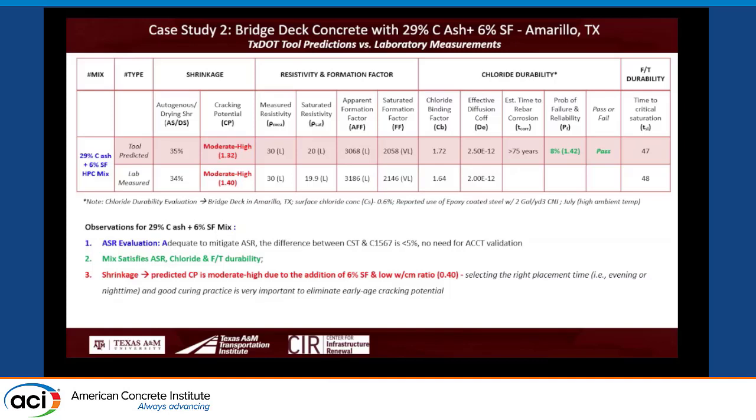That was not the consideration of TXDOT. TXDOT says drying shrinkage, all the mix packs drying shrinkage, so they are okay. But the high performance bridge deck concrete truck ticket shows use of a 0.39 water cement ratio. A 0.39 water cement ratio with silica fume is going to introduce some amount of autogenous shrinkage, which nobody considered. So autogenous shrinkage is a little bit high.